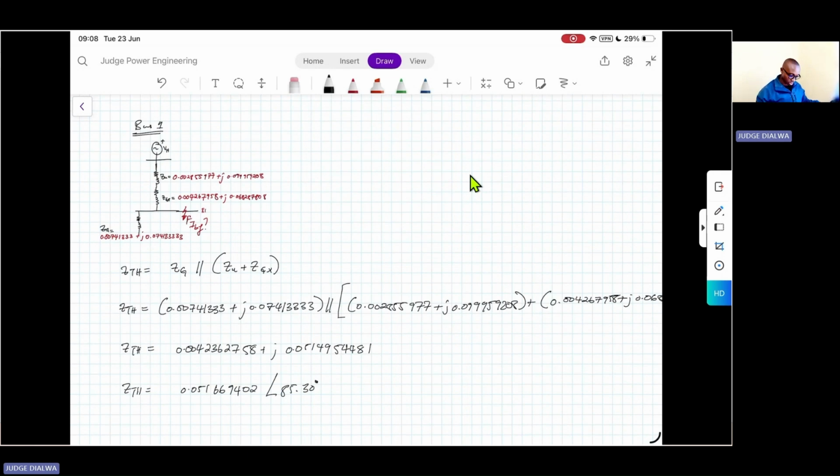Well, we'll then use this formula. The fault current will be our base MVA, which is 100, divided by √3 multiplied by the voltage of the bus. And the voltage of the bus that we are faulting, if you check in our last video, is the 15.75 kV bus.